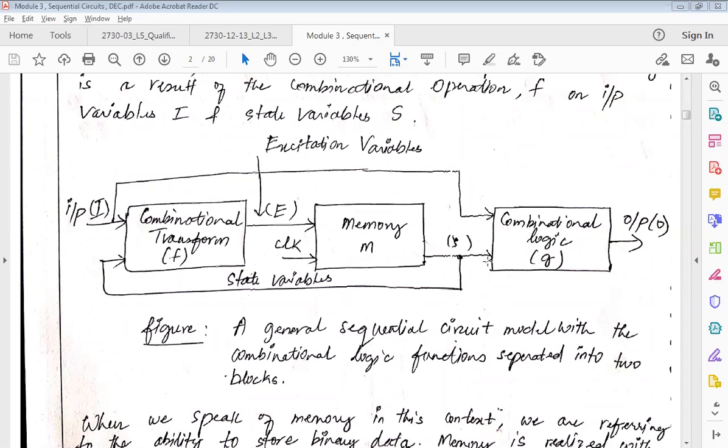combinational logic. Just remember, it will not have a memory element, which means it is instantaneous. As soon as I give the inputs, it will work out inside and give me the outputs. Either you take the output or you store it somewhere, that is your headache. The circuit will only compute based on the equation. So if I have AB plus BC plus CD as an equation, I will design my circuit in such a way that it performs this function.